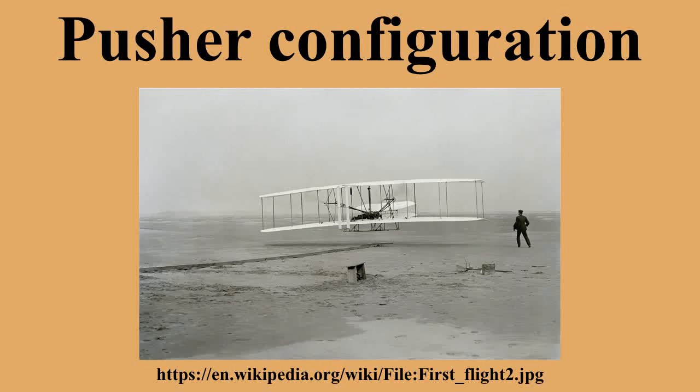Henry Farman's pusher Farman 3 and its successors were so influential in Britain that pushers in general became known as the Farman type. Other early pusher configurations were minor variations on this theme. The classic Farman pusher had the propeller mounted behind the main lifting surface with the engine fixed to the lower wing or between the wings, immediately forward of the propeller in a stub fuselage called a nacelle.